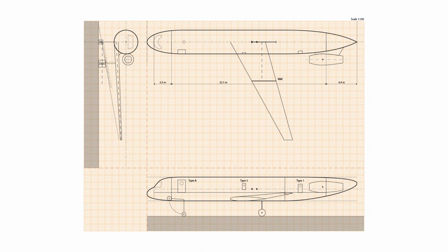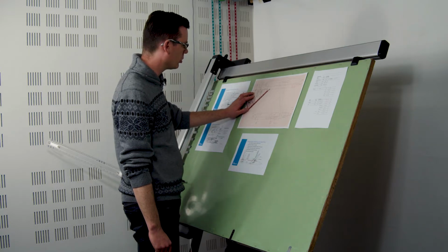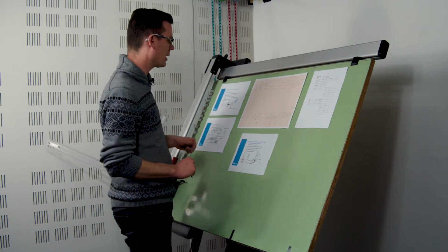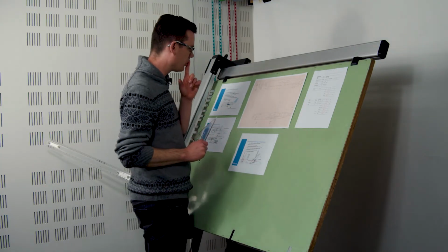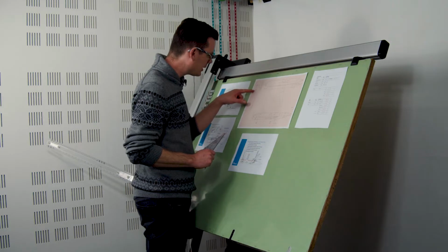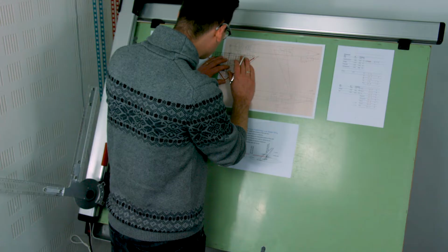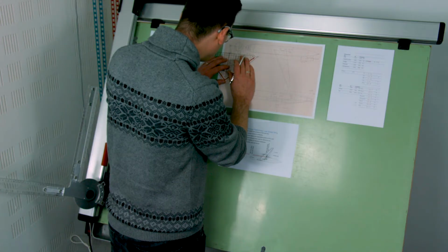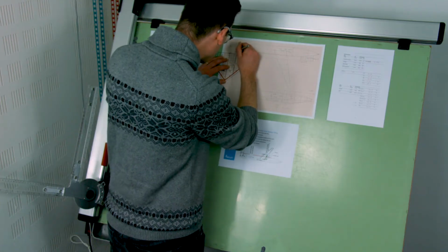And then finally I'm drawing in the strut. Well, now that I'm thinking about it, this thing also needs to be stowed, right? So it needs to collapse inside the fuselage if you stow it like this. So I'm wondering, now that I'm drawing it in, if I rotate this thing, can it actually be stowed? So let me take a look at what the length is going to be of the strut when fully extended, and I choose the hinge point inside the wing.